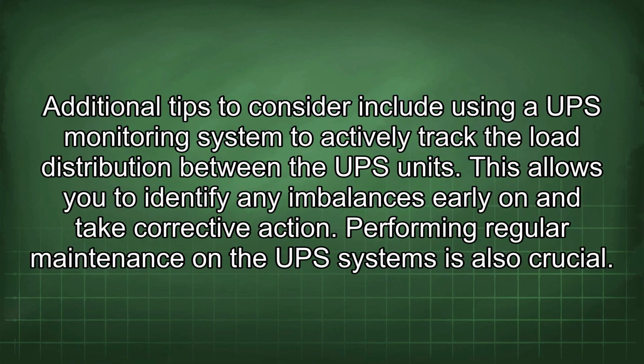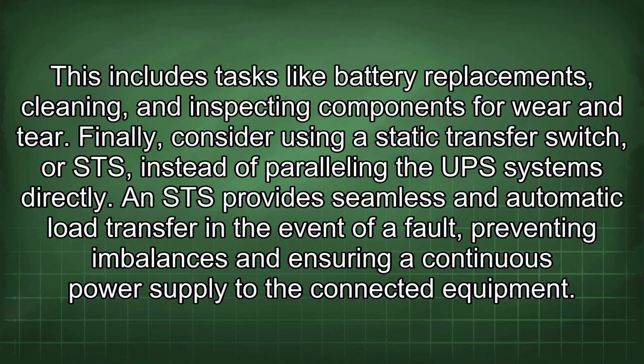Additional tips to consider include using a UPS monitoring system to actively track the load distribution between the UPS units. This allows you to identify any imbalances early on and take corrective action. Performing regular maintenance on the UPS systems is also crucial. This includes tasks like battery replacements, cleaning, and inspecting components for wear and tear.